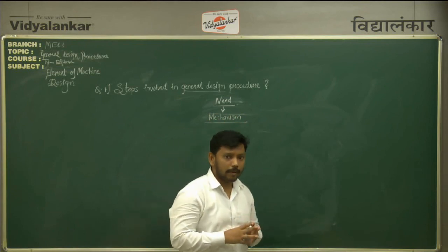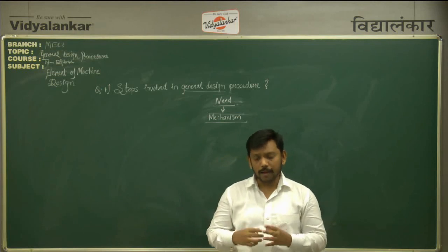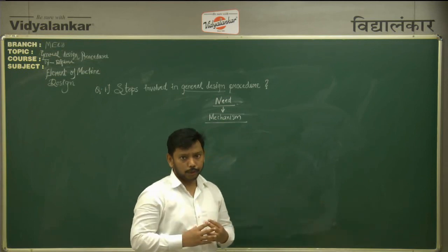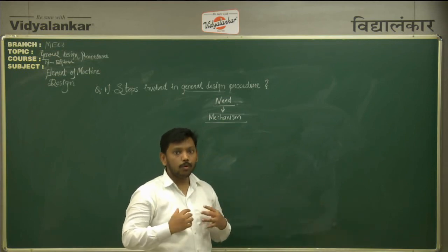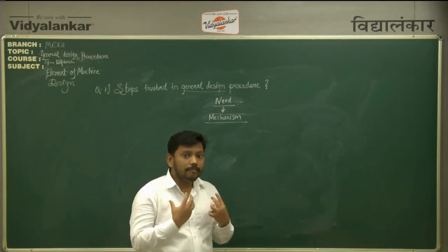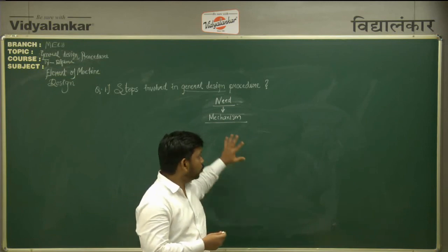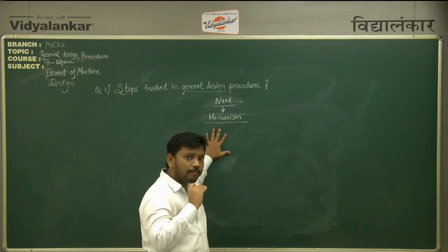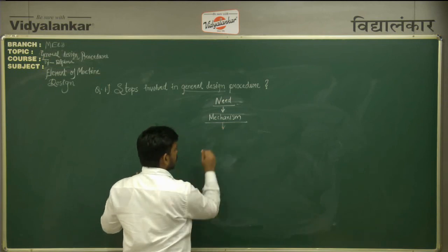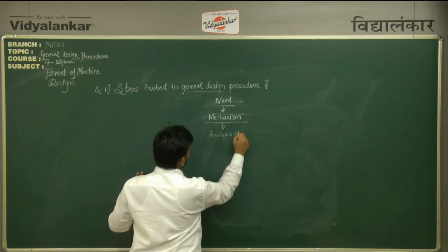Now once we have decided the mechanism, the third step involves doing certain analysis of forces. Why? Because when I tell you that I want to build a compressor, you will also ask me a question: how much pressure do you want to create in that compressed air? For example, if I say I want to create 50 Pascal pressure, then you need to design the machine, or the forces should be such that a pressure of 50 Pascal is created. So the third step involved in the design procedure is nothing but doing analysis of force.